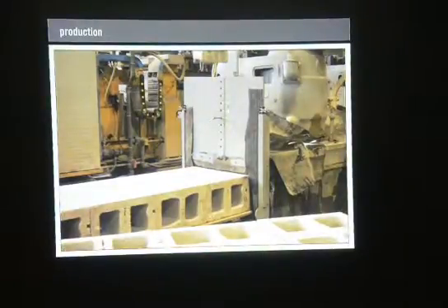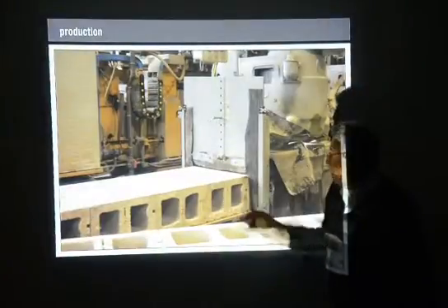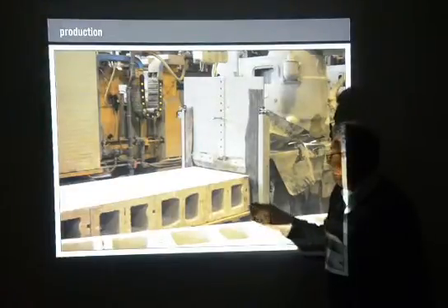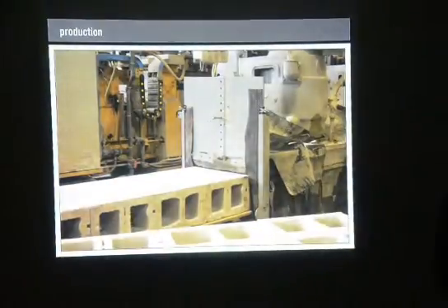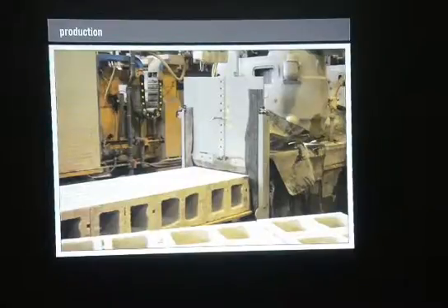Okay, now here, what's happening is this assembly is getting ready to break the block. Why are they getting ready to break the block? Because they're going to make it into a texture block that we know as split-faced block. So this is actually a splitter, is what it is. Okay? And basically, what we have is split-faced block for a lot of walls and buildings that have what looks like peaks and valleys in them. They're not straight, they're not symmetrical, they're a little bit out in some areas and a little bit in. They're concave and convex technically, okay? That's a good way to put it probably.